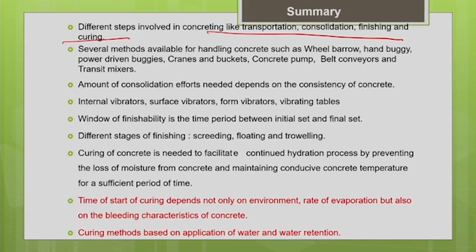Basically, there are so many methods available for handling the concrete. We have discussed simple methods like wheelbarrows and buggies, and advanced methods like pumping, belt conveyors, cranes and buckets and transit mixers. The selection of the method you are going to use for handling your concrete purely depends upon your productivity requirement. Every method has its own productivity.